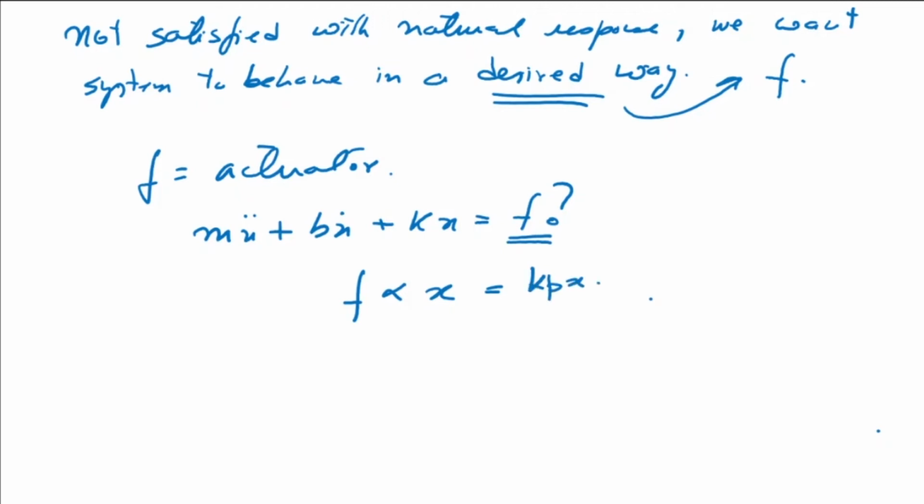It should also be proportional to the velocity, equal to kv times x dot. If I put only the first term, the system is going to overshoot the point and start oscillating, so there should be something changing with time, and that is my kv times x dot.